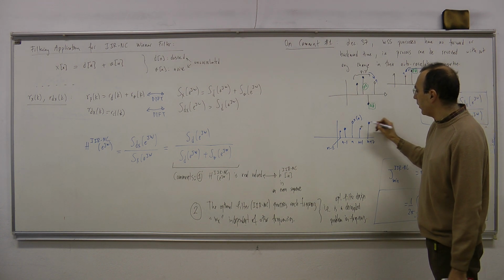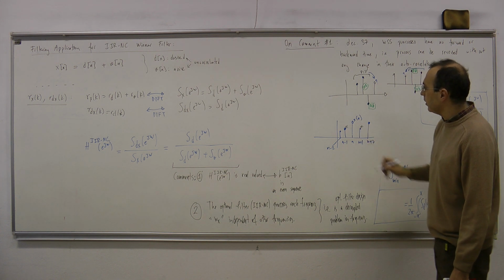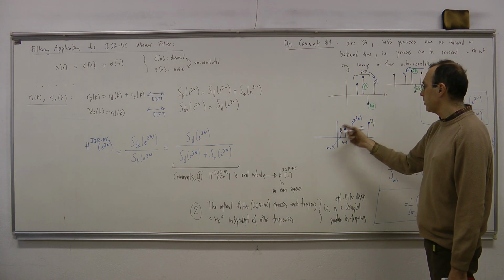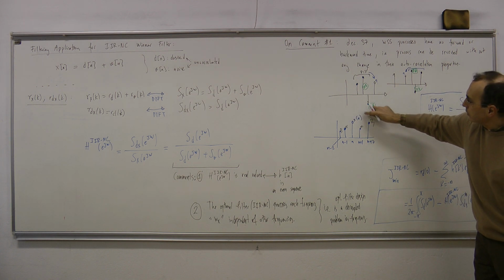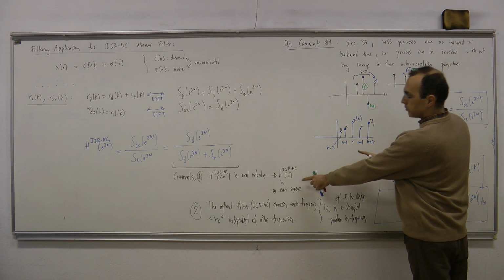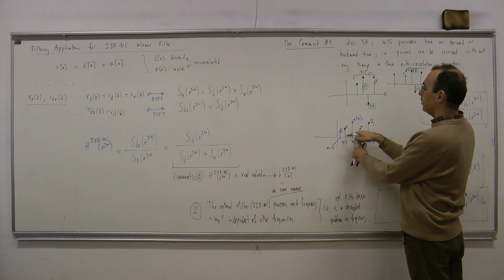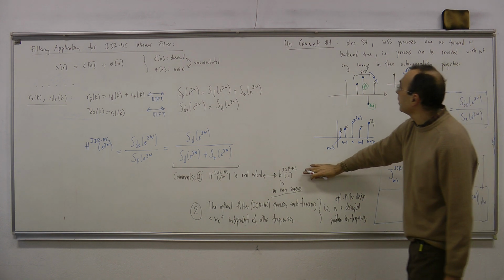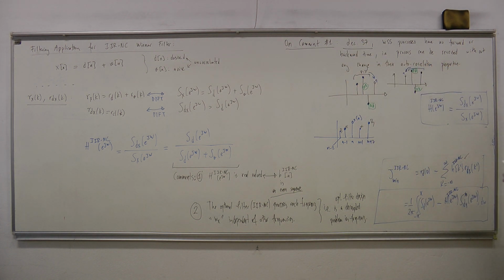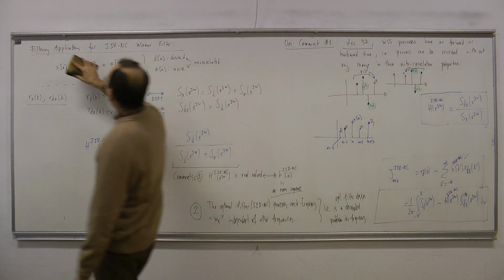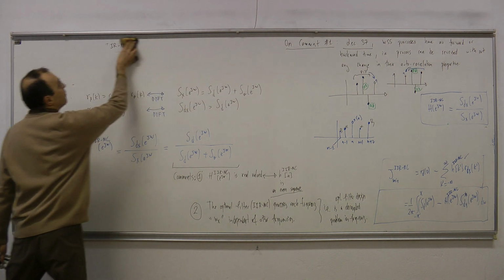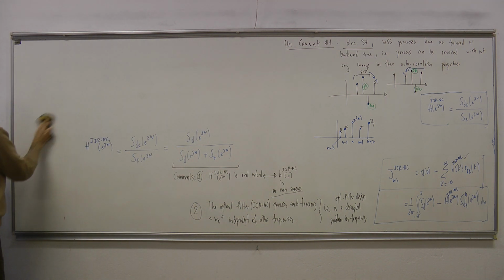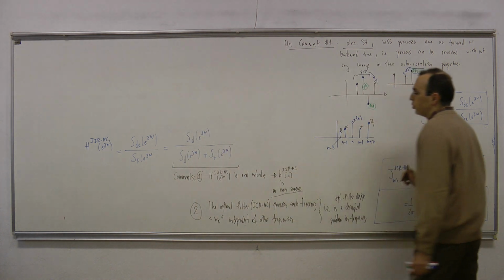So if you assign a weight alpha for this one in the processing, then you should also assign the same weight over here, because it can be the flipped process. If this weight is assigned as beta, this is also beta. So this means that the optimal coefficients for the filtering operation have to be some kind of an even sequence, because the one after and the one before are equivalently weighted because of the symmetry in time. So this is somewhat like an explanation of that from lecture 37. This is our interpretation. Because the process can be flipped in time, the linear combination weights, weighting the future samples or the past samples, should be equal to each other.